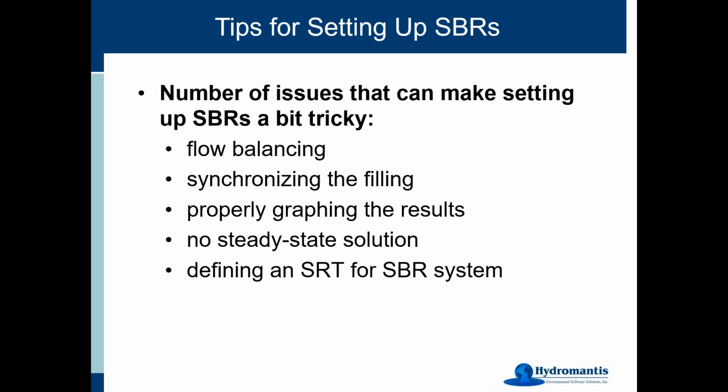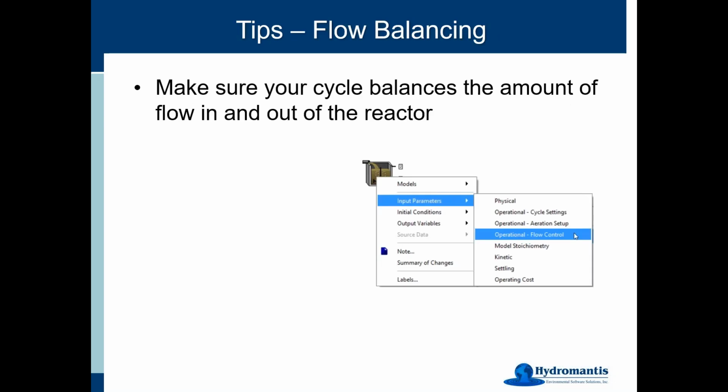There are a number of things that, because of that sort of starting and stopping nature of an SBR, can make setting it up a little bit tricky. So one of them is, of course, that flow balancing that I mentioned earlier, synchronizing the filling to get that upstream flow to start at the right time and stop at the right time, graphing the results, and a few other things. So let's take a look at each one of these in a little bit more detail here.